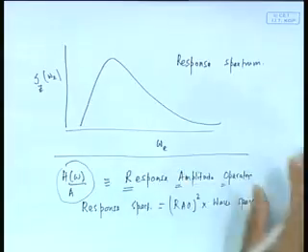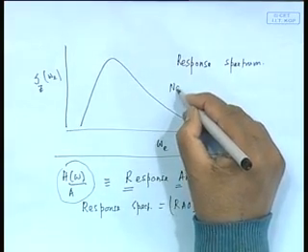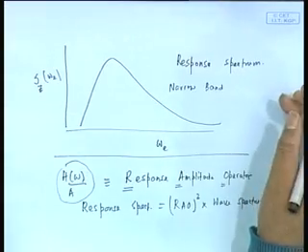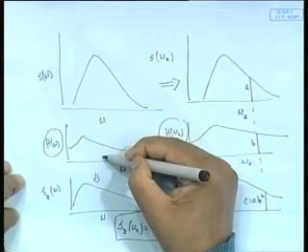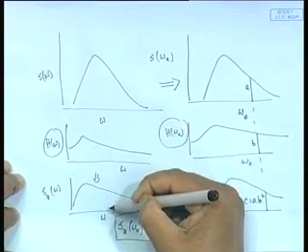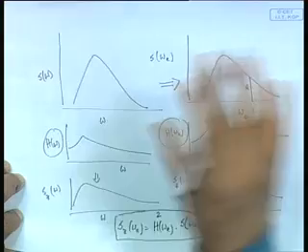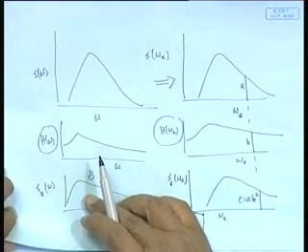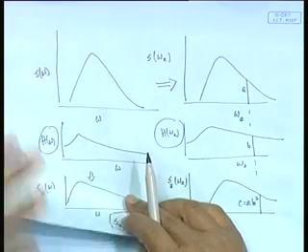Now, if I were to assume that to be again a narrow band, and this is what people say, that the RAO, multiplied with this narrow band Rayleigh spectrum we discussed, the presumption is that it does not change too much the shape as far as statistical quantities go. So, it is presumed that this also is fairly well represented by a narrow band Rayleigh spectrum, although you have seen that if I see this following wave, things look very different. But we will come to that again.